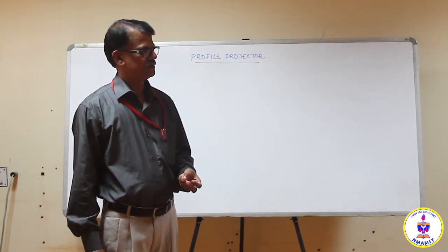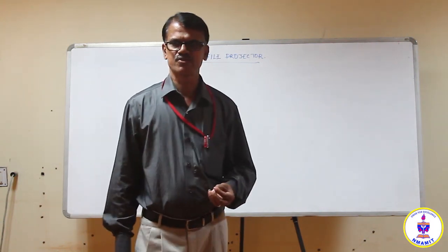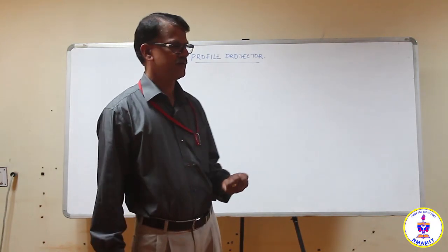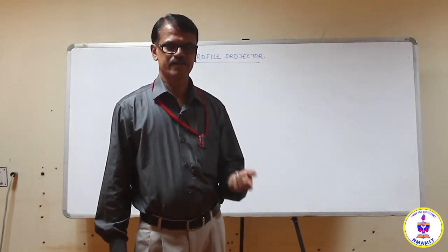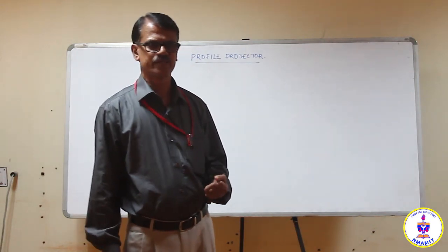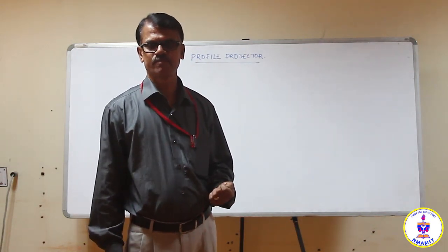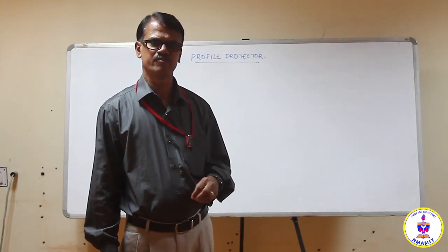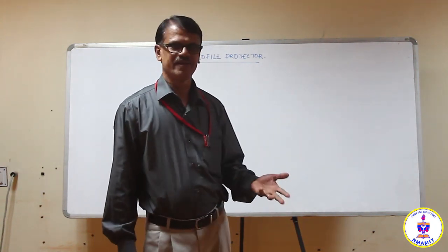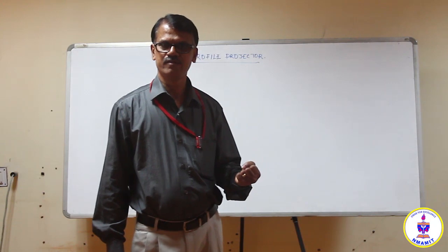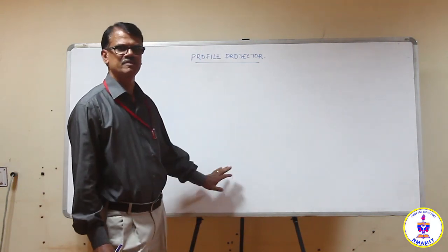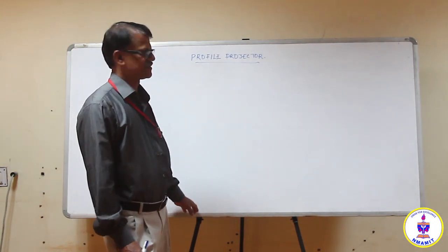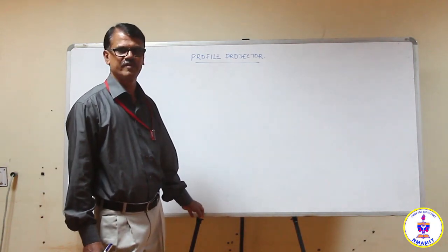So due to the restrictions of size and geometry of a component, if it is not possible to measure directly by conventional measuring instruments, any physical parameter can be measured conveniently by projecting a magnified view of that feature on a screen, and the measurement can be made on the screen. So that is the working principle of profile projector.